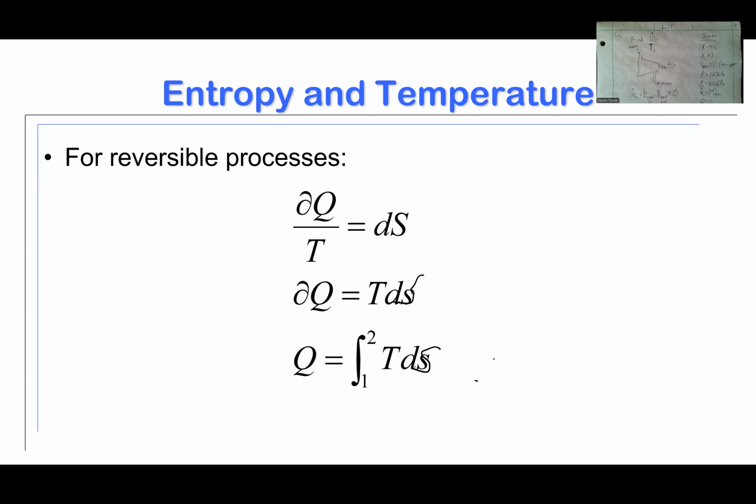At any rate, similar to the fact that, remember, work is equal to the integral of pressure with respect to volume. So if work is equal to the integral of pressure with respect to volume, heat, in the case of a reversible process, is equal to the integral of temperature with respect to entropy.